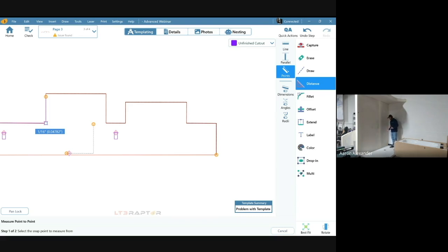Now, once we establish this wall, create level and plumb, and shoot it, check our measurements, make sure we're good, we can move the laser anywhere we want to then set a plane on this wall, shoot the ceiling, shoot the left wall, shoot the bathtub base possibly, shoot the floor, run plumb up off of that, whatever you might want to do there. But we could move the laser wherever we want for each page.